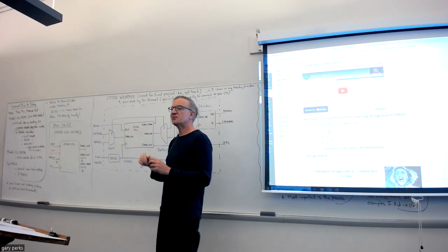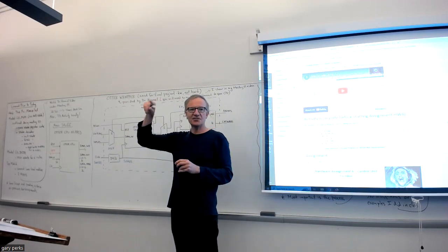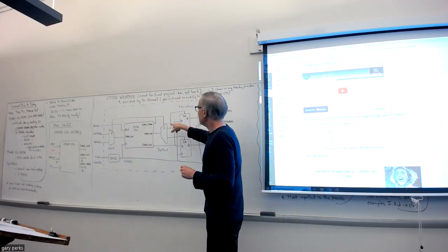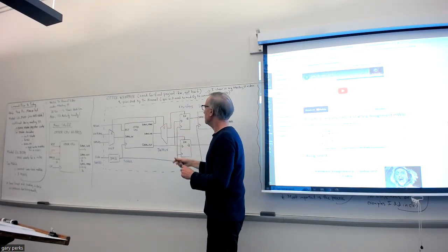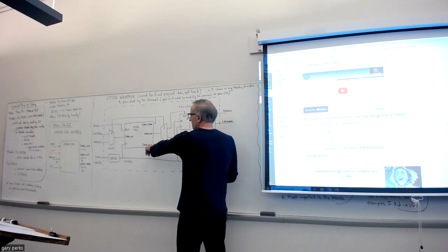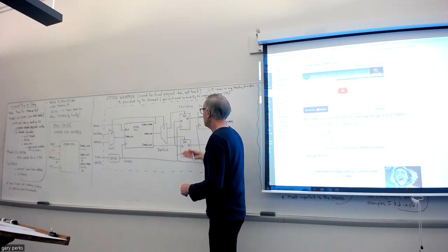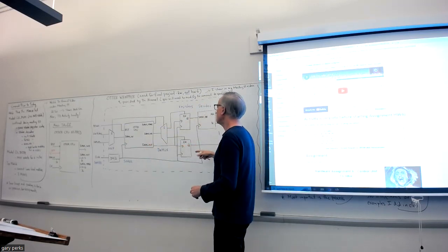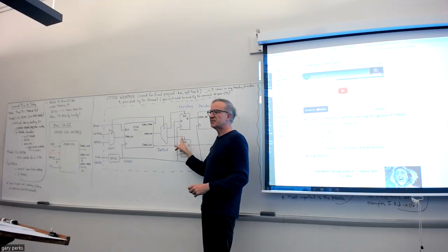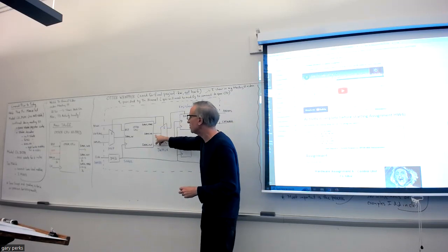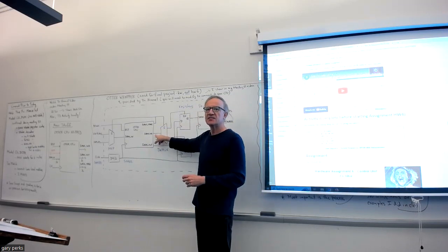Right, it's the switch address plus 20, right? It's 11.0.0.0.20. So that's the address we would have here if the output data is coming from this IO bus out. Okay, but that output data won't pass through the register unless the enable is activated. And it's an active high enable, and that's coming from this IO bus.